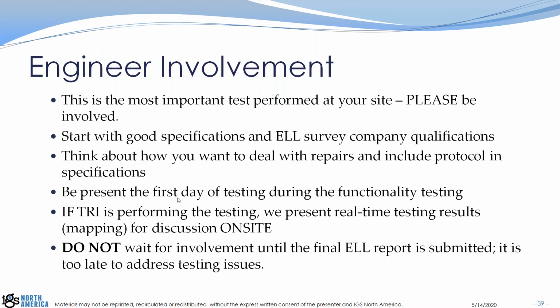Also, I strongly encourage you to be there the first day of the testing. During the functionality testing, you should be there. So if there's any issues with site, with functionality, or site prep, you get it. That is the time to address it, not after the fact. When I do testing on site, I will show my voltage map to anybody on site who will come and look at my computer. It's all about the voltage map. That shows the quality of the test. If the map is ugly, I want the engineer to know. If the map is beautiful, I want the engineer to know. And most of the time, they don't know until they get the final report back. And by then, it's too late.